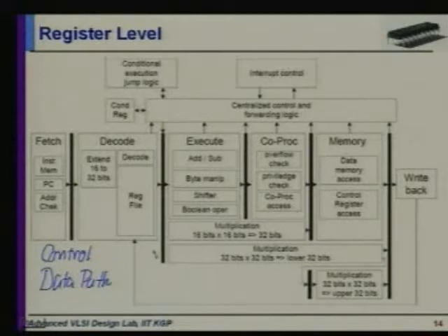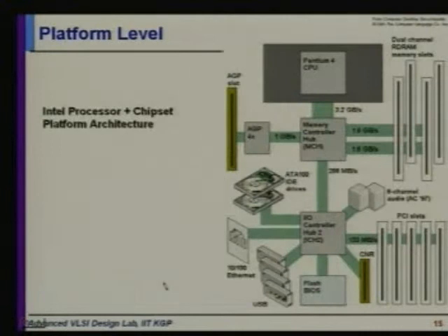So the task of the synthesizer is to take the register transfer level description, extract out the control and the data path, synthesize the data path and the controller as separate entities, and then integrate them together to get the overall design of the chip. So it's a completely non-trivial process, and we'll go through that once.